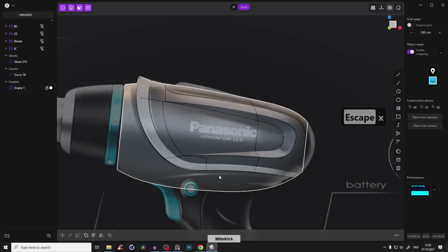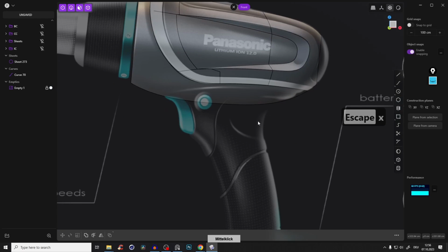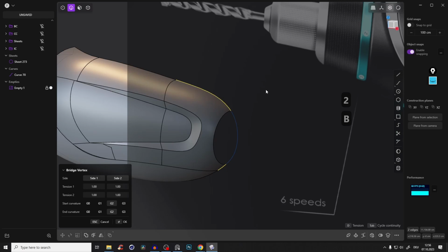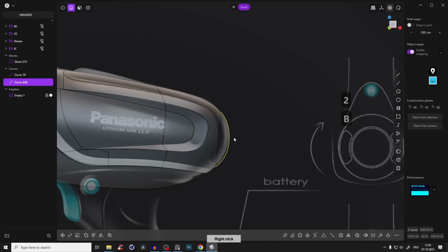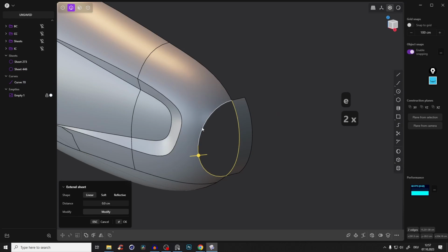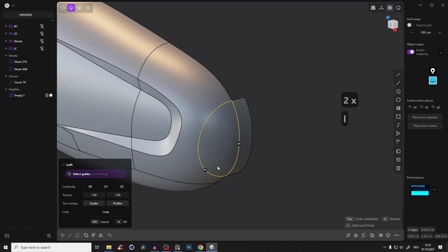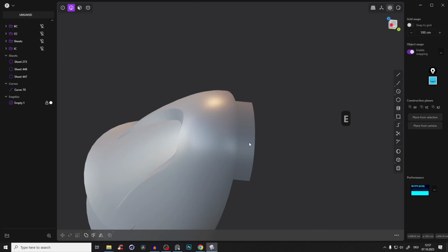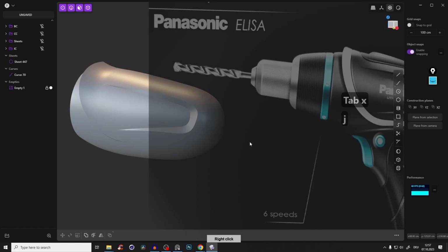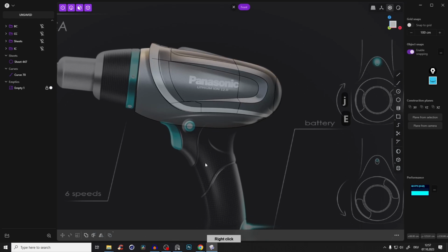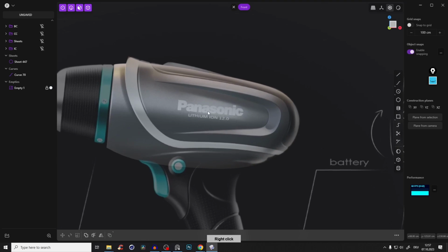Okay, so let's continue here, because we still have some interesting stuff to do. Let's close our hole at the back. It looks a little bit weird. So Shift B, and close that hole. Select that, extrude that a little bit outwards, and now you can loft that or patch that. You have to see what results will be better. Yeah, that looks absolutely fine. Again, it's not perfect, but it will absolutely do our job here.